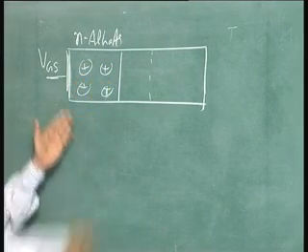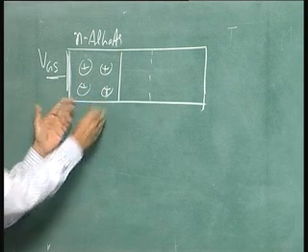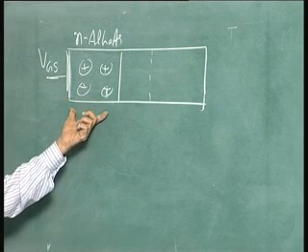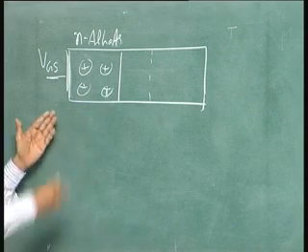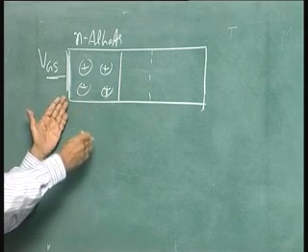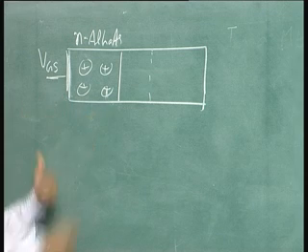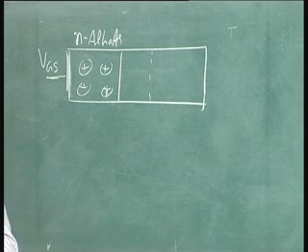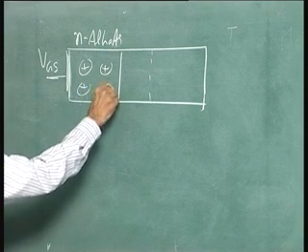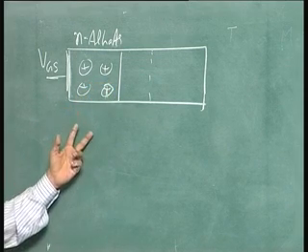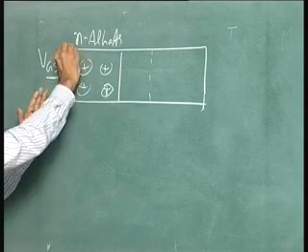Okay. We know that the voltage required to deplete the entire layer is equal to VBI minus VP0. Okay. VP0 is the total potential barrier from here, but if there is already VBI, the voltage required is VBI minus VP0. I think you have just forgotten the formula that is used for the MESFET. This portion is the equivalent of the MESFET.